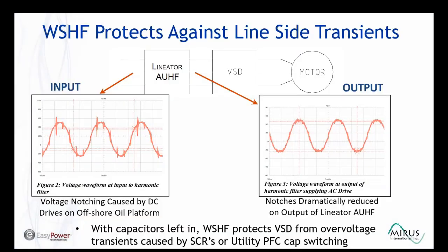And if leading power factor is a concern when using passive harmonic filters, they can be equipped with capacitor switching contactors that operate under lightly loaded conditions. As I mentioned earlier, some harmonic filter designs require contactors because their capacitor reactance is quite high. But when properly designed, they aren't necessary. And in these instances, keeping the capacitors in the circuit under all loading conditions can save the cost of the contactor and can also help in protecting the variable speed drive from line side transients.